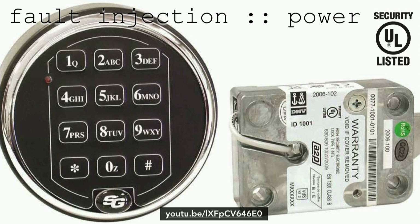Every time you enter an incorrect pin, it writes to EEPROM and says, this person performed an incorrect pin, and I'm going to have a timeout. It's kind of like on your phone, if you enter the wrong code over and over again, it will start to back off, or have a time delay. So they said there's also a reset attack, where you reset the chip so that it doesn't remember this person just tried 3 incorrect codes, make them wait 10 minutes. However, they thought about that and said, no, we're going to write to the EEPROM that this person just entered an incorrect code, so even if they try a reset attack, we're still going to know exactly how many times they did that.